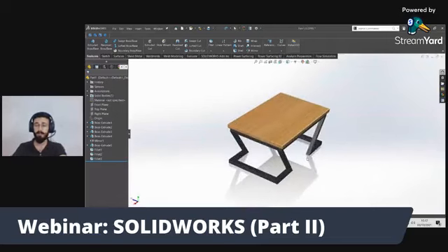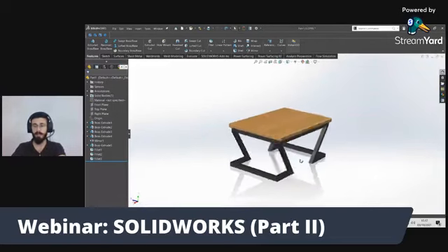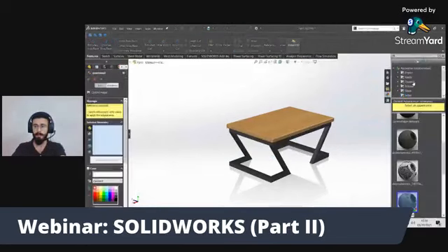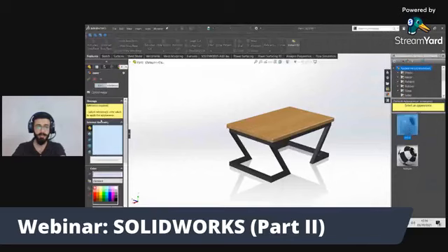this is the use of appearances and rendering. Like this, I have just added appearances and materials. I haven't yet rendered it. How do you add an appearance to your model? Just go to here. There is an option here. See, it shows edit appearance. Just click on it. Appearance, color, and there it gives you options.